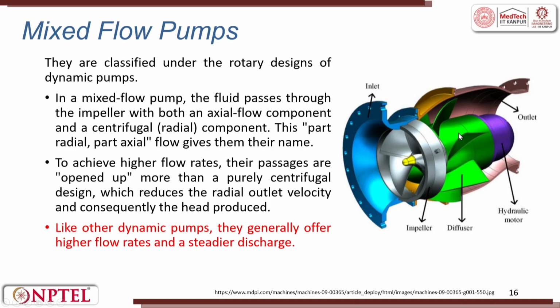So, when we get into mixed flow pumps, they are classified under the rotary designs of dynamic pumps, the classification we saw in the beginning. In the mixed flow pump, the fluid passes through the impeller with both an axial flow component and a centrifugal component.